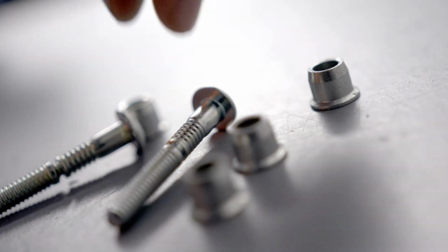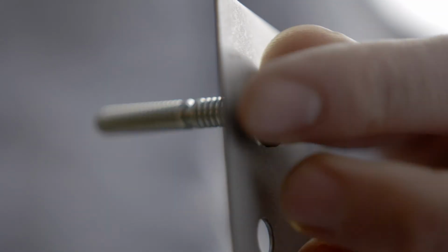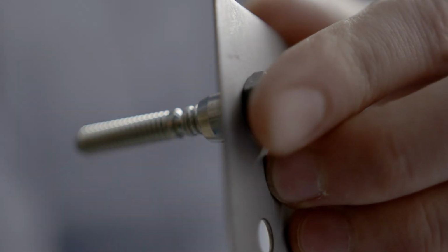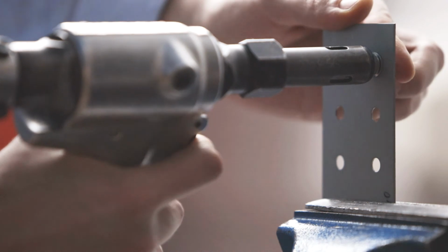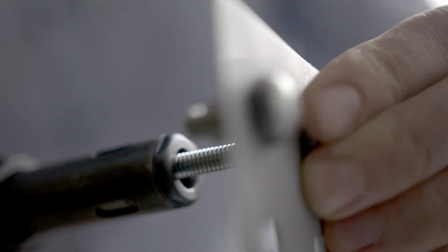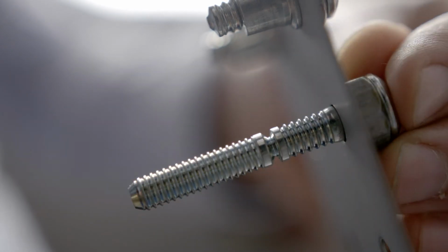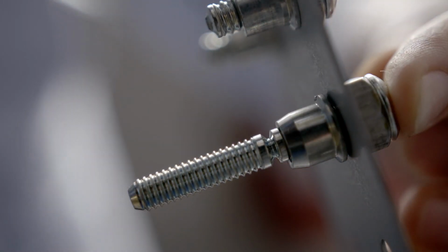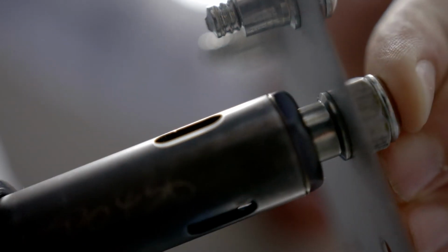After we have now discovered the world of blind rivet nuts, we are going to a high-strength fastening solution which is called lock bolts. Lock bolts consist of a separate pin and collar which are mechanically locked during the installation process. These fasteners form joints capable of withstanding the toughest applications and environments that traditional rivet and screw joints often cannot provide. They offer exceptional resistance to vibration and material fatigue due to the swaged lock which forms collar material permanently into the circular grooves of the bolt.